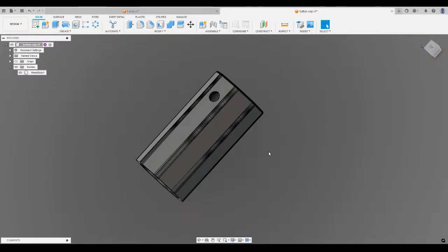Yep. Okay, it was as easy as that. Prismatic was the one we were hoping for, but we were able to solve that pretty easily in Fusion with the delete key. And what was the other option that we had to go for? Other than prismatic? Faceted. Okay, and that brought it in as a poly mesh, or took the poly mesh and turned it into a solid body object that we could then work with. Yeah.